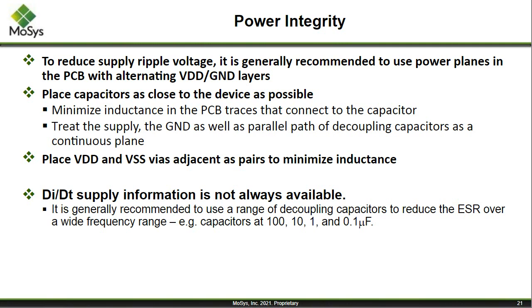But the planes that deliver the power to the device, you want them kept as solid as possible. You don't want to cut them up. And so that's an important issue to try and undertake, even if it's multiple layers down. If you can keep as big a plane as possible, that's important. The next would be capacitors.